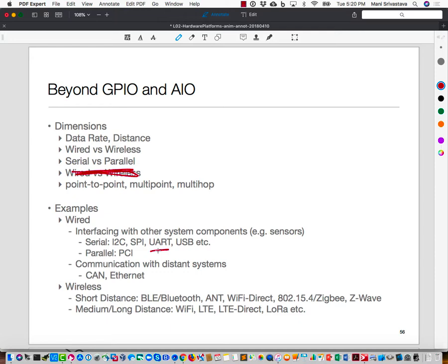And then many times nowadays MCUs also have radios built in, because wireless ways of talking with other peripherals and other nodes have become very common. Bluetooth, or Bluetooth Low Energy mode, is a radio which you will find quite a bit in fitness kind of stuff. It has been overtaken by BLE, but older exercise machines and all often have it. And Wi-Fi Direct is a particular mode of Wi-Fi where two devices talk to each other directly, like your iPhone has Wi-Fi Direct.